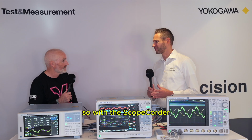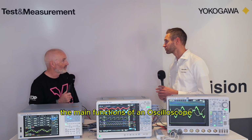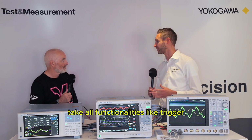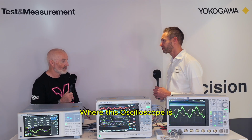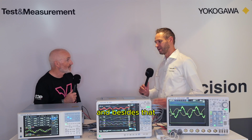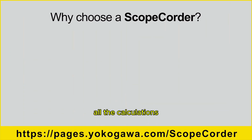So with the ScopeCorder, you can take benefit from the main functions of an oscilloscope. So that's also where the name comes from, at least the first part, ScopeCorder. So the scope will take all functionalities like trigger, like measurement capabilities from an oscilloscope. But where the oscilloscope is aimed at very short phenomena, the ScopeCorder will be able to capture for a much longer period of time. And besides that, it can also do some power measurement functions and other calculations during this time.